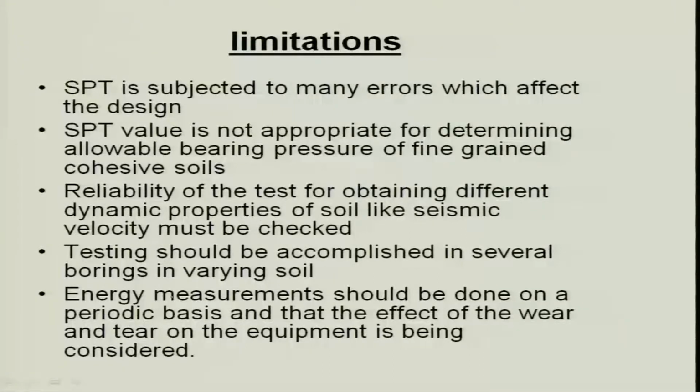So, what are the limitations? SPT is subjected to many errors which affect your design. SPT value is not appropriate for determining allowable bearing pressure of fine grained cohesive soils. Reliability of the test for obtaining different dynamic properties of soil like seismic velocity and shear velocity must be checked. Testing should be accomplished in several borings in varying soils. Energy measurement should be done on a periodic basis, and the effect of wear and tear on the equipment should be considered.